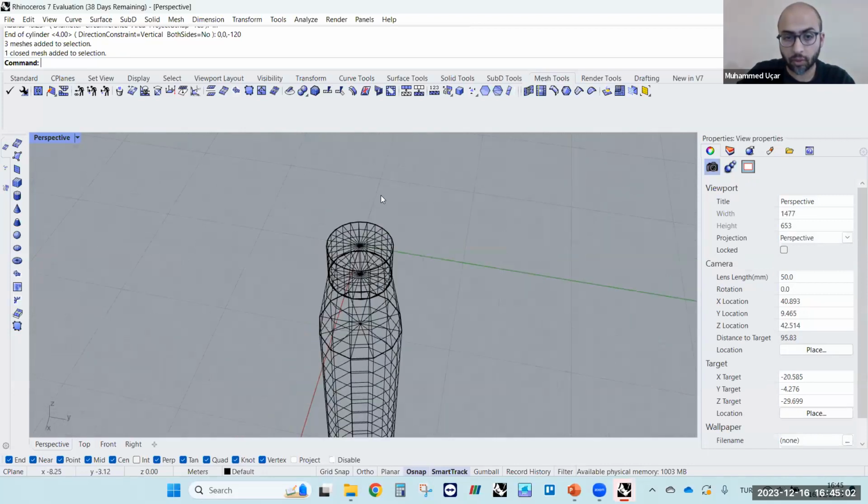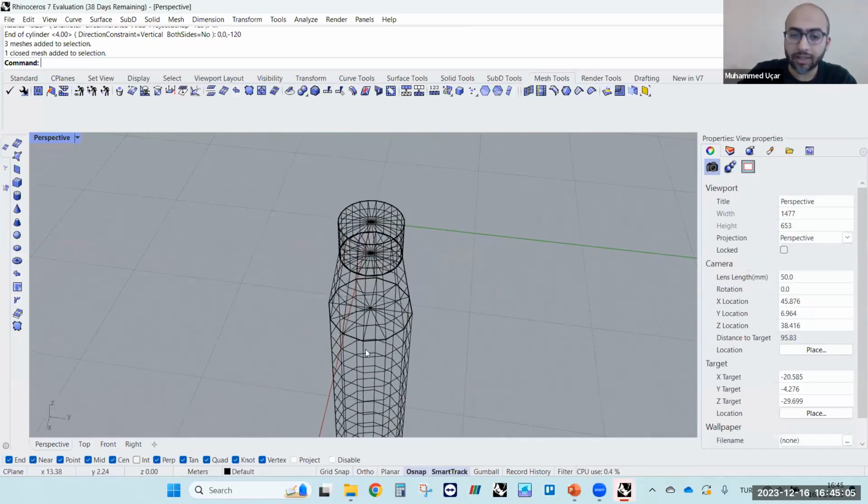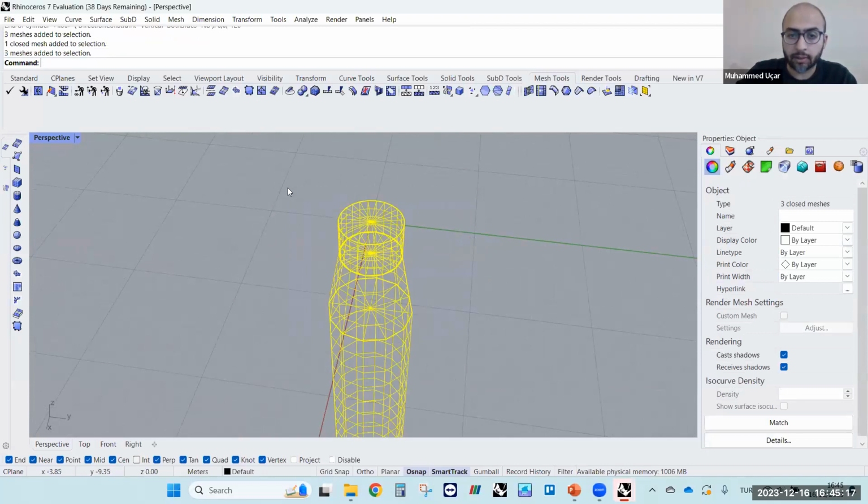We need to join them, but before that, we need to cut it if we want to gain more computational advantage. For coarse geometries, there's no need, but I will show you in case you will be using finer geometries. If the mesh number is decreased to half, then the computational time requirement will be decreased to 1/4. That's why we use that option.